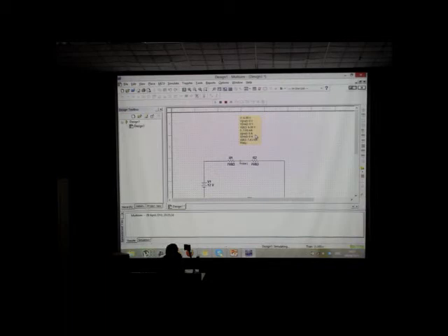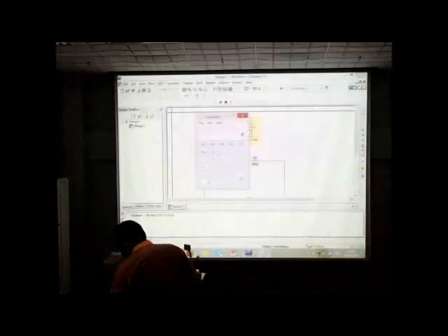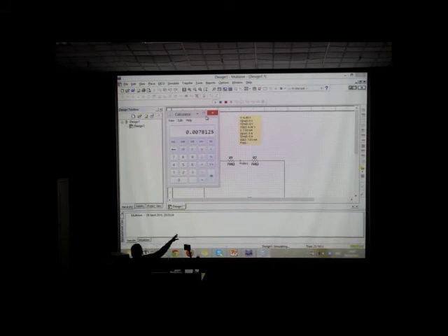If you want to see the current, you just divide 12 by 768. Let's just see how it works. We have 768 plus 768. Okay, it's 1536. So when you divide 12 by 1536, you get 0.007825, and that would be our 7.81 milliampere. So you can see it shows the current in the circuit, and the voltage at exactly that point, and everything else.